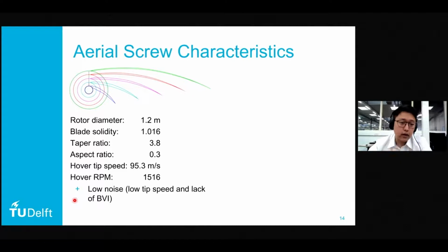One downside to having a single bladed rotor is that you have an oscillating center of lift. The center of lift is located somewhere in the middle of the chord between the leading and trailing edge. And as this rotor rotates, of course, the center of lift rotates, which gives some torsion in the central airframe, which should be addressed, as it could give fatigue failure.